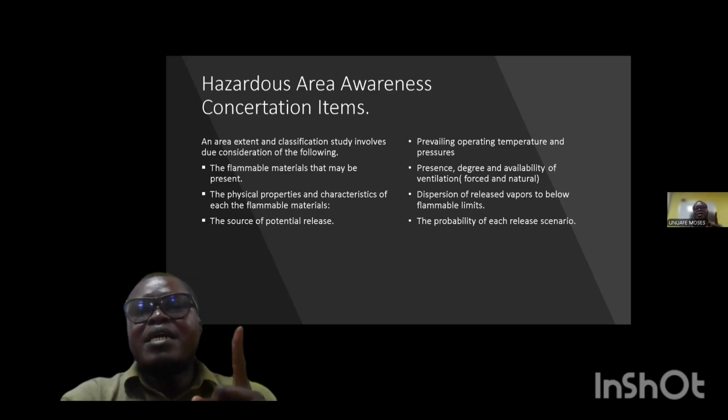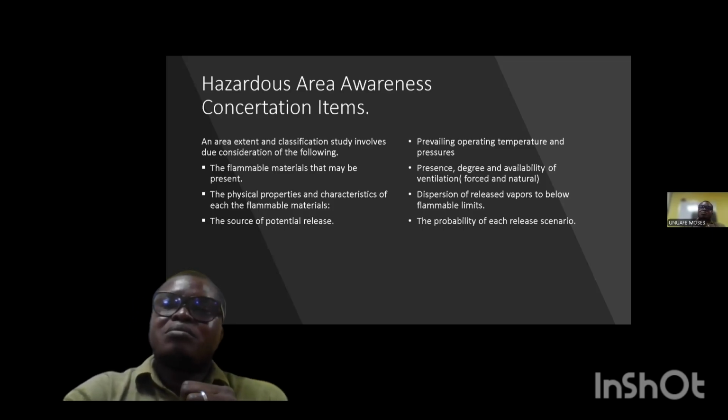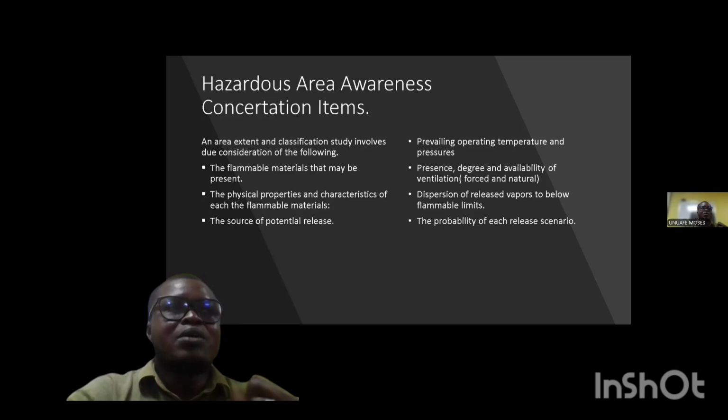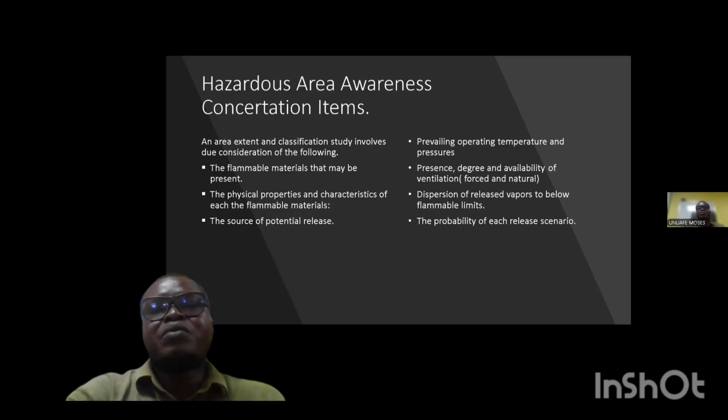In hazardous area classification, just like I said, the concept is used to determine the grade of release, which is categorized according to IEC 60079-10-1. This considers continuous, which is a frequent happening; primary, which is happening occasionally; and secondary, which is happening rarely.